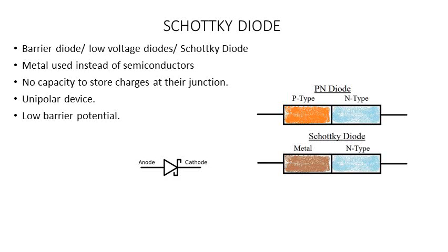The diffusion capacitance usually restricts the switching speed, and the transition capacitance will decide the frequency of the reverse switching operation of the diode. So a smaller value of these capacitances is required for higher frequency of operation of the diodes. Schottky diode usually has almost zero diffusion capacitance and a smaller value of transition capacitance.